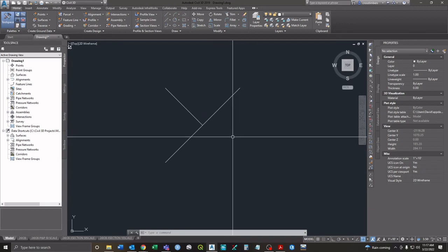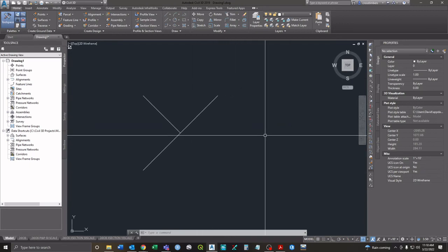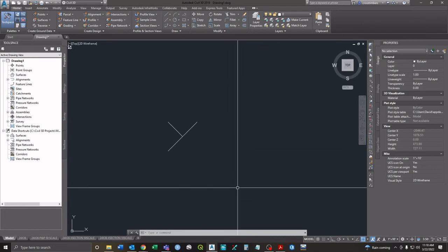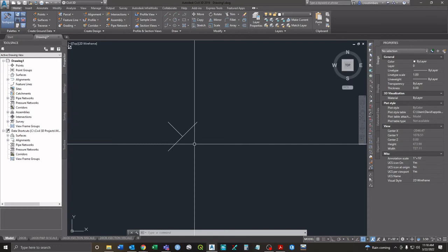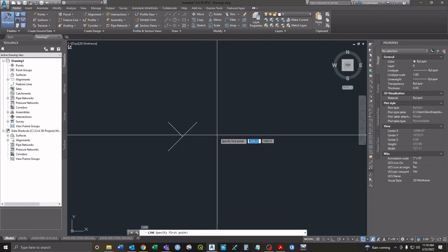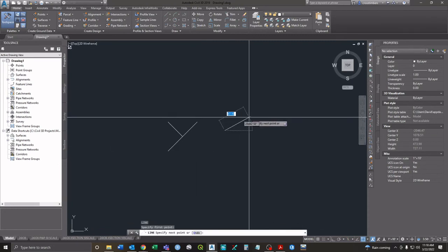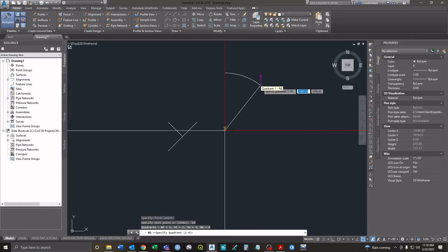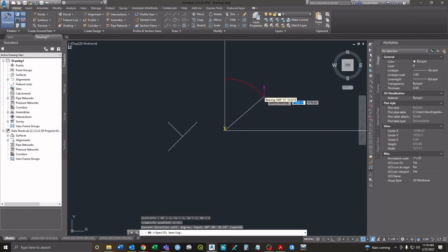If you ever have to draw, instead of just highlighting, say you're highlighting the center line or the section line in the right of way, you would have to actually draw it in at that bearing. That's how you have to draw it, or you have to write it. So again, that was just line, enter, you specify the first point, and then apostrophe BD. You pick your quadrant, so you can just click on one, and then it says specify bearing.